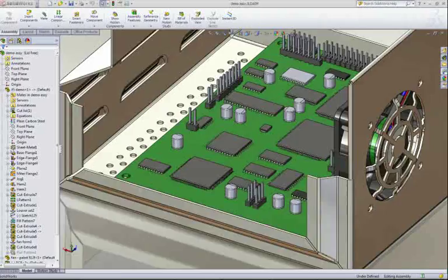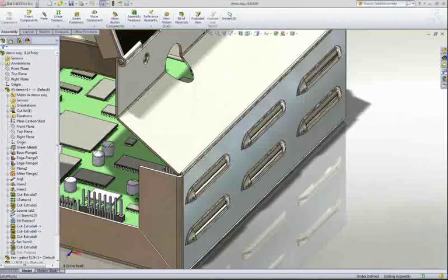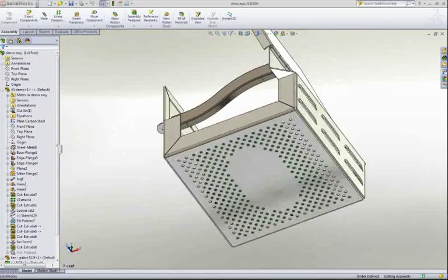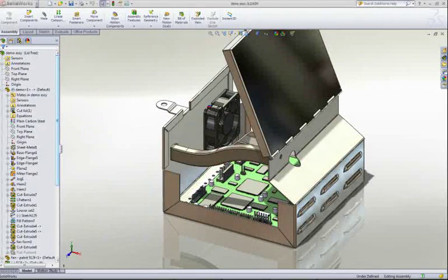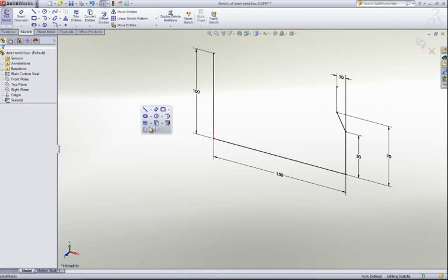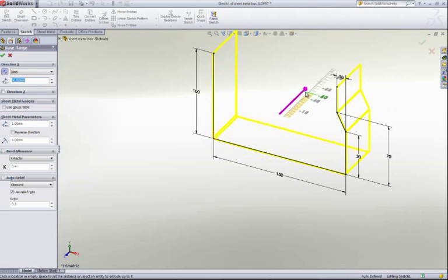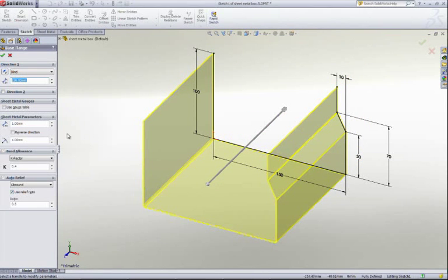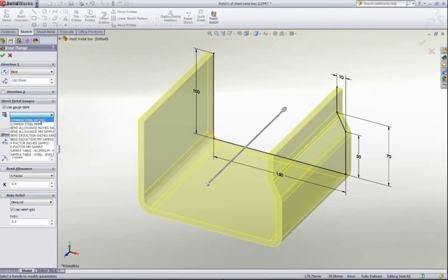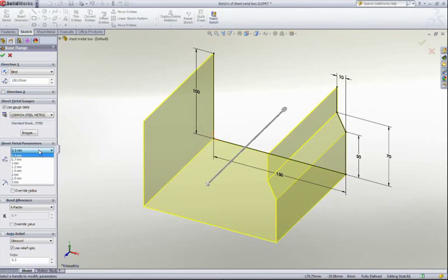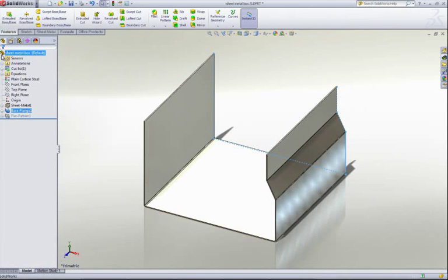Your CAD tool should not limit your creativity. You need the flexibility to create sheet metal parts in the manner best suited to the job in hand. We'll look at top-down assembly design later, but for now, we'll concentrate on the basics. Material selection should be your first consideration. In sheet metal design, we are often forced to adhere to certain requirements, such as standard materials and in-house standards for manufacturing and tooling. You need a simple way to make sure you comply with those standards. SOLIDWORKS offers a customizable gauge table, which contains only the materials, thicknesses, and bend radii that are readily available in our shop, so there's no need to look it up each time, and you'll keep tooling costs to a minimum.